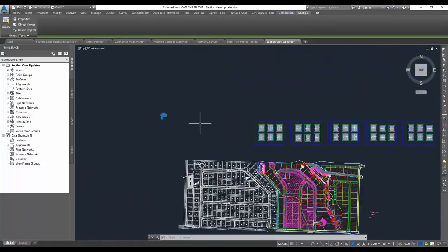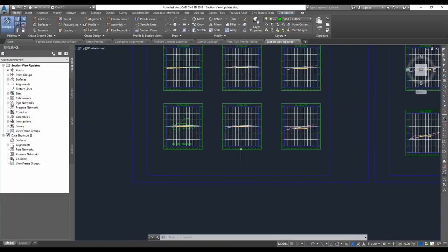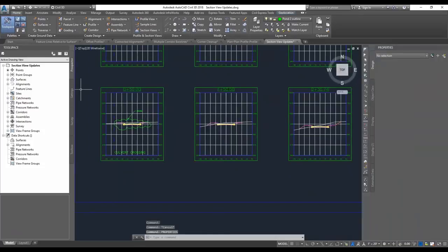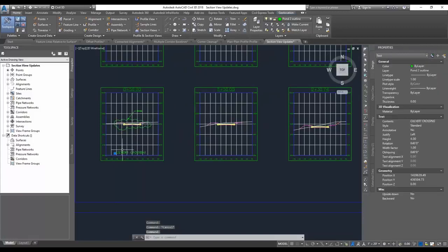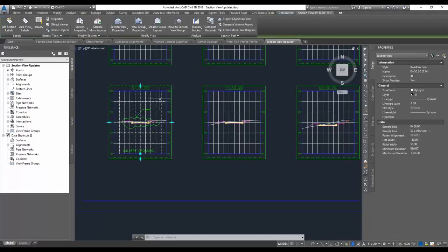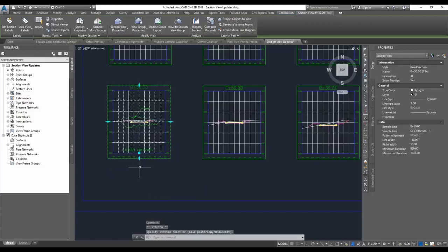Now I've got some pre-baked stuff over here. I'm just going to move this over. So all this is an M leader. I'll show you in the properties palette there. It's just an M leader, polyline revision cloud, and a piece of text. Okay, if I select this border around my section view, see, I have these grips here. These are for the section view drafting buffer. Okay, so everything inside that drafting buffer is going to move along with my section view. So if I move the whole section view, notice all of those manual notation elements move with it.